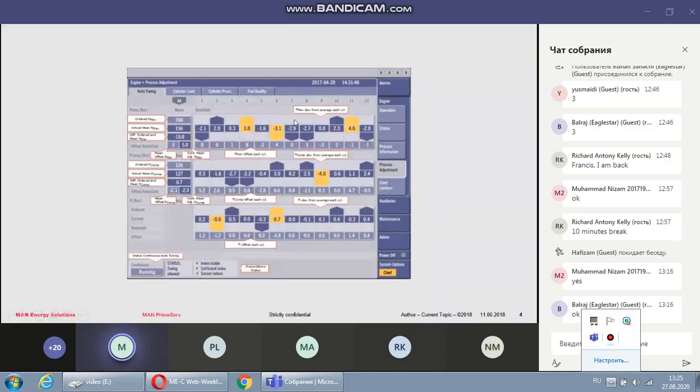Once you do the tuning of the units, balancing all of them, then you can go for continuous tuning. So what do you have to do for that? You click this button. Then it will show you continuous, Pmax continuous. There will be an option here. Click on it. So the Pmax will be automatically adjusted all the time till you push this 1 second.